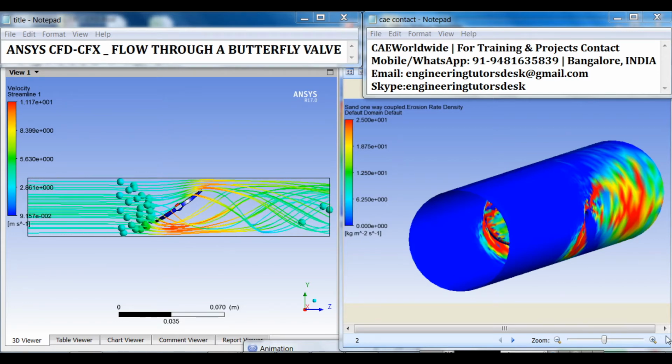The fluid material for the flow analysis is water, which flows at a certain velocity through a pipe of diameter d that has a rough internal surface. The velocity profile is assumed to be fully developed at the pipe inlet. The flow, which is controlled by a butterfly valve set to an angle of theta to the vertical axis, contains some sand particles, of size range in microns, having a particular value of equivalent sand grain roughness, using a rough wall boundary to simulate the pipe wall in CFX-Pre.